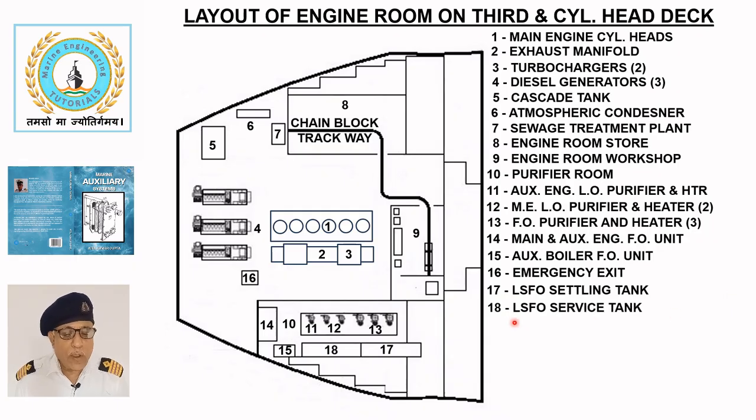Low sulfur fuel oil service tank. The low sulfur fuel oil service tank 18 receives purified fuel oil which is then supplied to the diesel engine for consumption. The service tank is always kept full with excess fuel overflowing back to the settling tank.